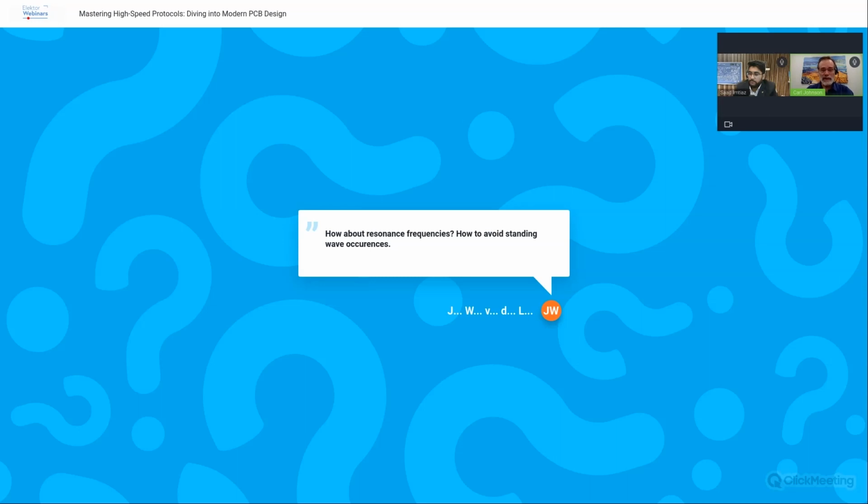It's really interesting. So what's the fix though? Remember, we want to take all the research and elements and the history of everyone around us and develop best practices that get away from that. We're not trying to develop the science per se. What we're trying to do is execute the science. So in this case, a slight variation of the via distances will prevent that kind of resonance cavity from forming in the first place.